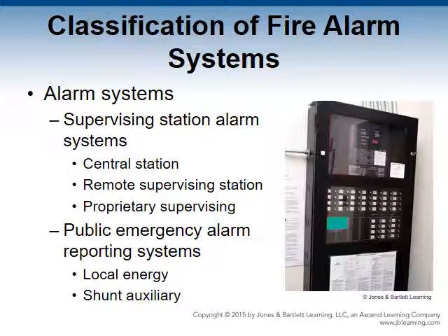Proprietary supervising fire alarm systems establish building and property owners as the responsible party to monitor the fire alarm system signals at their facility. They typically consist of a number of fire alarm systems on a property spread throughout an area or region, or in a building under control of a single user, transmitting signals to a central monitoring location staffed 24 hours a day by trained personnel who will take appropriate action upon receipt of the signal.